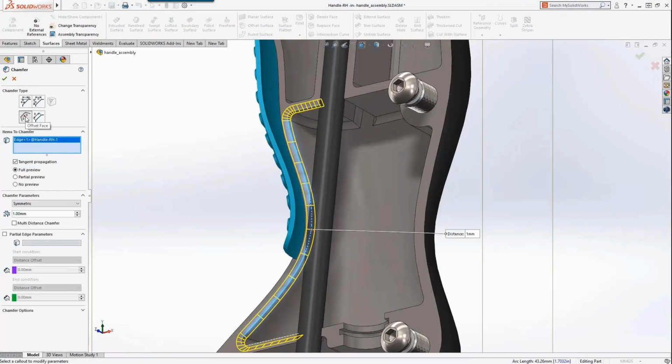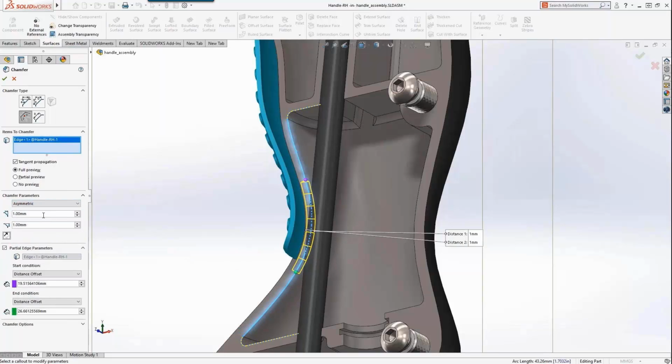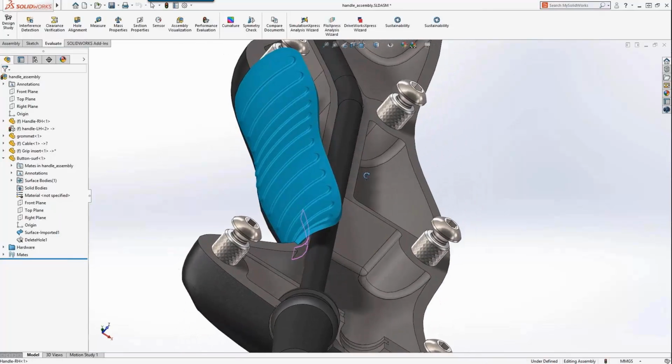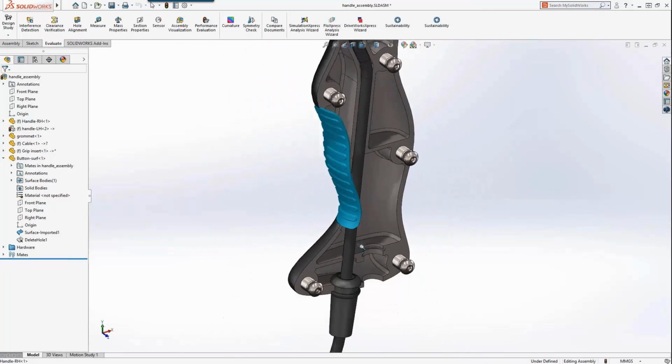As we move forward over the assembly, we do an interference check. We see that there's a problem with the interference here, so we want to add a fillet. There are various options available to control the start and offset, and the on-screen handles can be dragged to locate the ends of the chamfer. An asymmetric fillet or chamfer is supported as well. The new capability will save time and reduce the number of features.